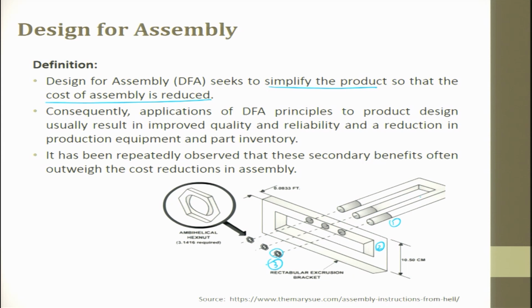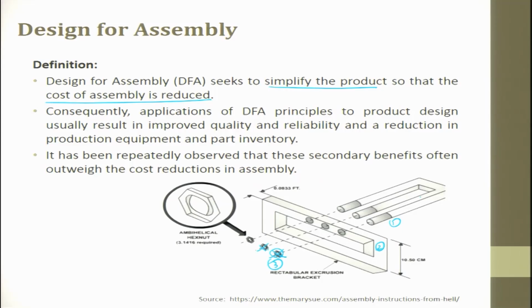If I wanted to apply design for assembly and try to eliminate the parts, what I will do is I will eliminate these nuts and make the threads internally inside the part. So, now what happens, the bolt or whatever this part is gets fastened to this base without using the nut.